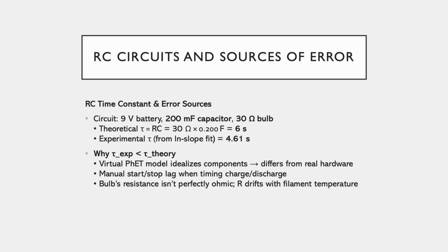In the physical lab, we'd also see lead resistance, battery, and capacitor leakage. So in conclusion, across all the tests, Kirchhoff's rules reliably predicted voltages and currents as long as our ideal assumptions held. But the RC experiments highlighted how resistance controls charging speed and how real world factors like temperature, timing error, and non ideal components shift results away from textbook values.